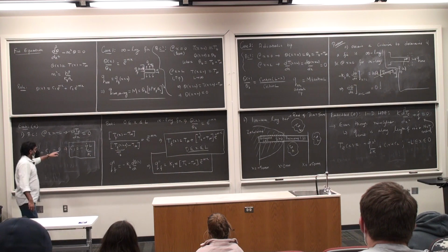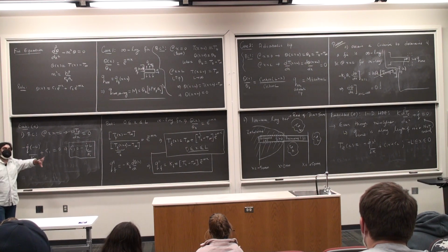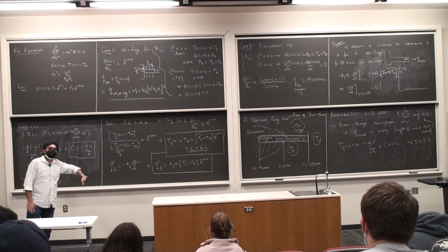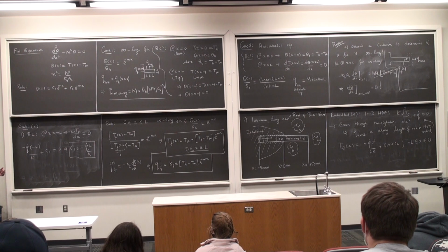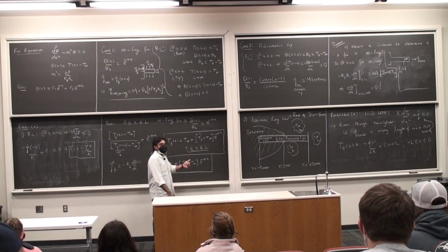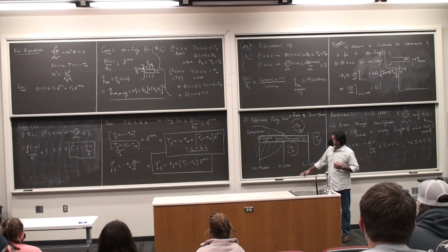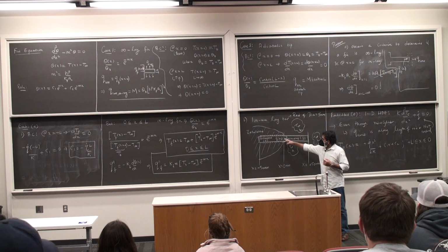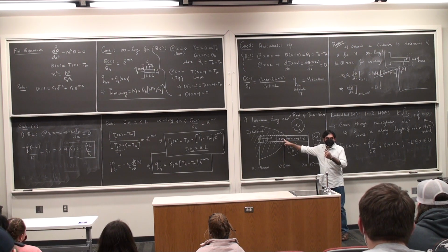We have used one boundary condition to calculate C1. I need two more boundary conditions. The boundary condition at the end of the fin has already been applied. It's an infinitely long fin with an adiabatic tip and so on. So the only boundary condition that is left is at the interface between the embedded wall and the fin. And it should be fairly straightforward to realize that this is going to have a continuity in temperature, and it will have a continuity in the flux.